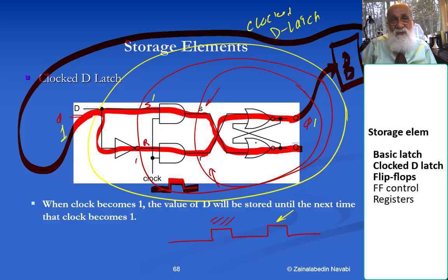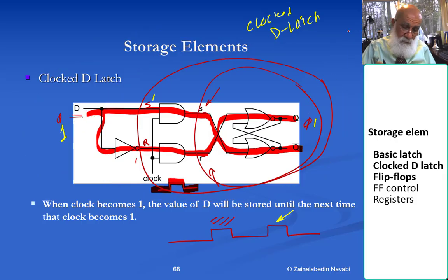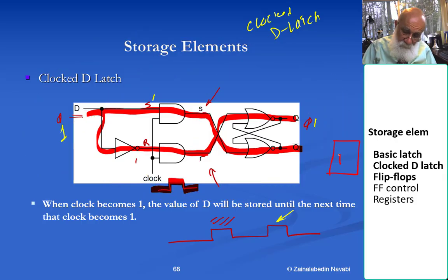I will have a situation that my circuit will be oscillating. Let's, for example, say that this combinational circuit on the upper right hand side is a, let me redraw it here. Let's say this combinational circuit is just an inverter. And this inverter is fed back into this.